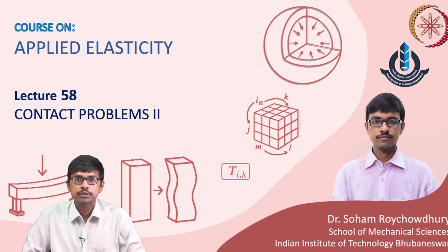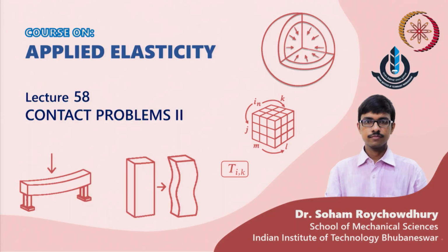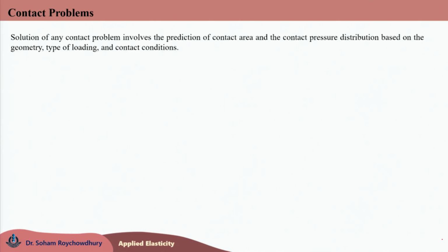Welcome back to the course of Applied Elasticity. In today's lecture, we are going to continue our discussion on the contact problems, which we had started in the last lecture. So, to have a quick recap, the contact mechanics problem basically involves the solution of the contact patch generated or the contact area and the contact pressure profile or contact pressure distribution generated within that contact patch.